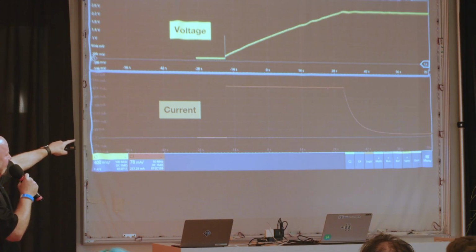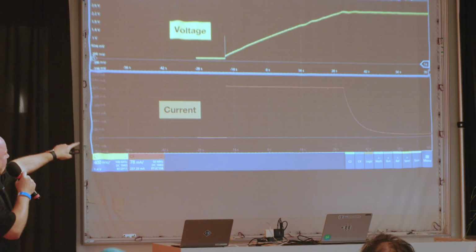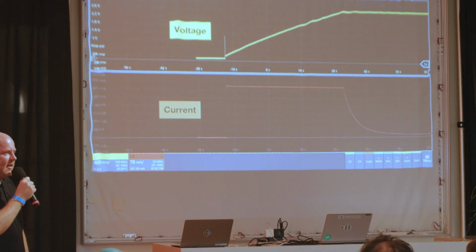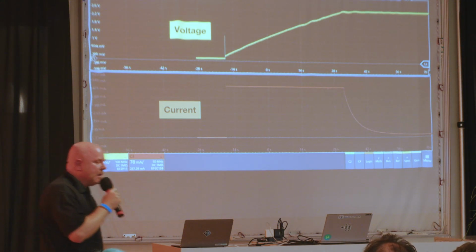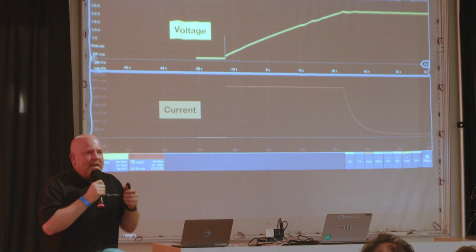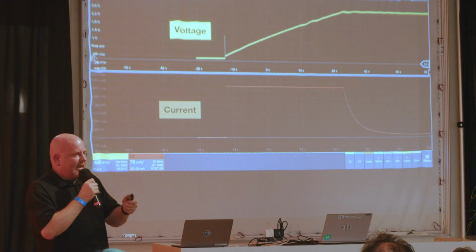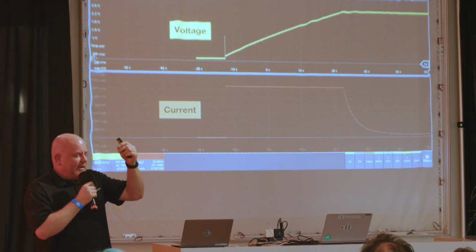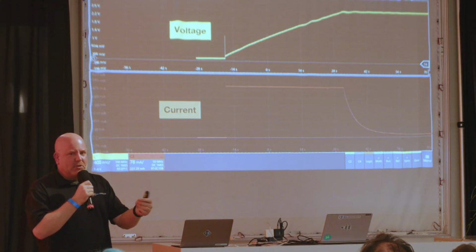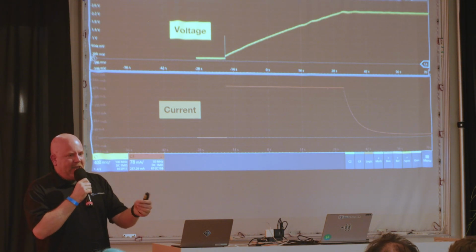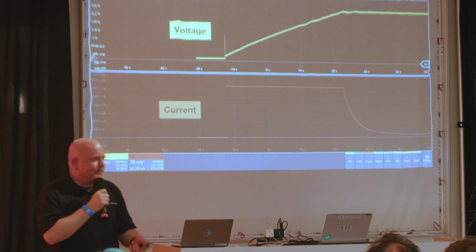And then after it gets really close to being fully charged, it has a charge that looks kind of like what you normally see with a traditional capacitor. The reason I point this out is because you really have to think about how you are going to charge this cap when it's dead. You can't just put it behind a solar panel and think the solar panel will ever be able to charge it up. It can't. You have to have some kind of charge controller.